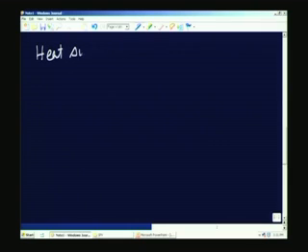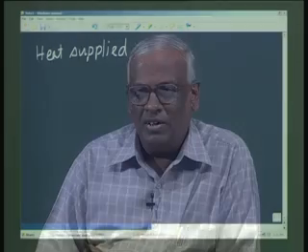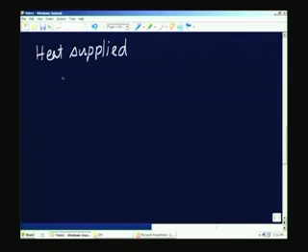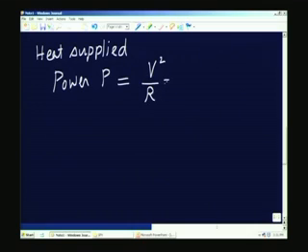Heat supplied under the steady state, of course, this amount of heat supplied has to flow through the specimen oil sample, or some of it is of course lost from parasitic losses through other channels, and therefore, the heat transfer through the sample is the difference between the heat supplied and the loss. So, heat supplied can be calculated as the electric power, which is given by V squared by R. This will be 40 squared divided by the resistance of 53.5 ohms.